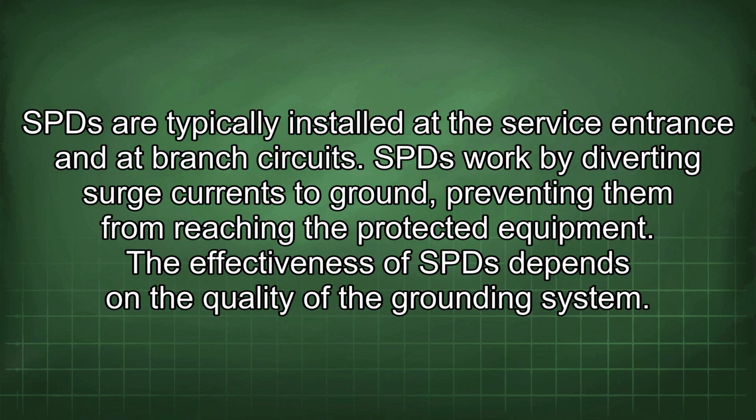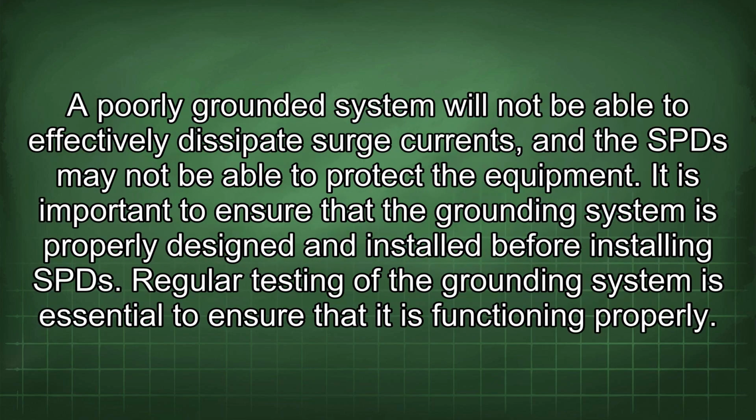The effectiveness of SPD depends on the quality of the grounding system. A poorly grounded system will not be able to effectively dissipate surge currents, and the SPD may not be able to protect the equipment. It is important to ensure that the grounding system is properly designed and installed before installing SPD. Regular testing of the grounding system is essential to ensure that it is functioning properly.